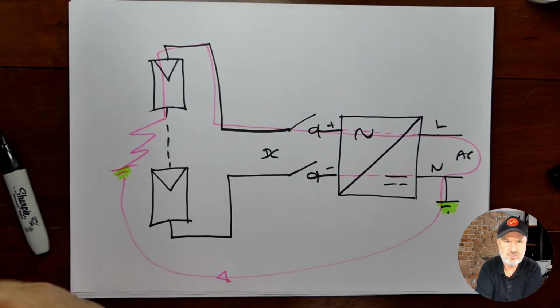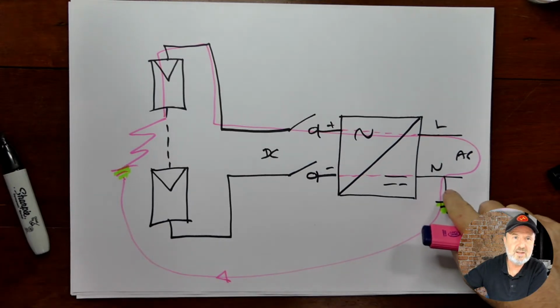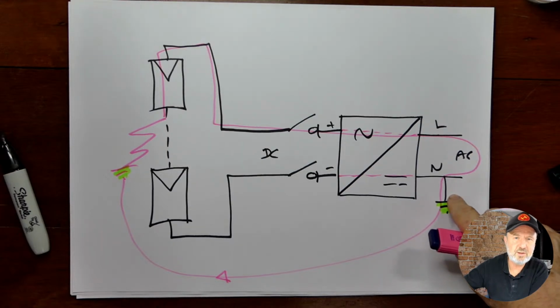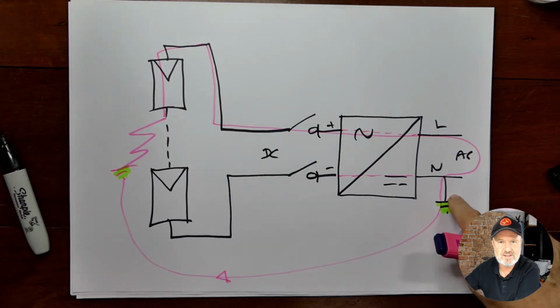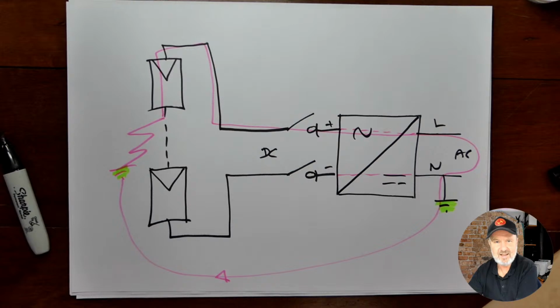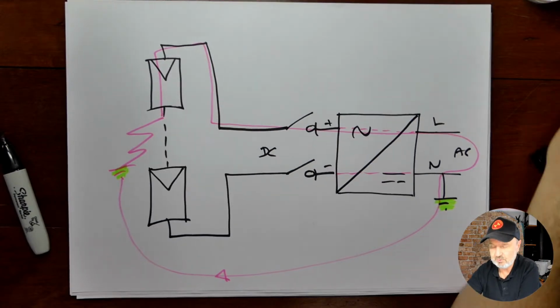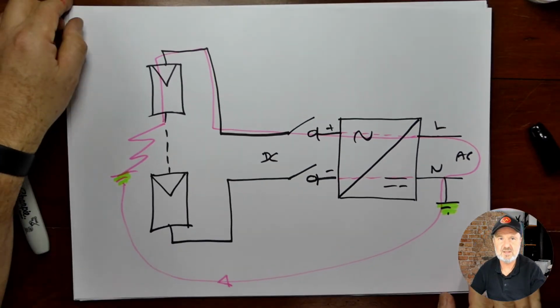So it goes right through the DC side, right through the inverter, usually destroying it, back through the transformer, back through the neutral, through the earth conductor, and that's a bit scary when you think there might be DC flowing through your switchboard, through your earth conductor, without you knowing about it. So removing the main earth could be a little bit hazardous.